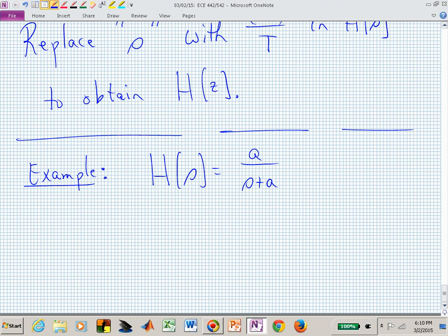You're filtering, you're attenuating higher and higher frequencies. As omega gets bigger, your H is getting smaller. That's a low-pass filter. You favor low frequencies because you just told me the DC gain was 1. At s equal to j omega with omega equal to a, you're now at that sweet spot. You're at the corner frequency. You now have the half power point. That's your break frequency in these straight line approximations. You could simply sketch a straight line magnitude response for your interviewer and say this is a low pass filter with a cutoff frequency of a.